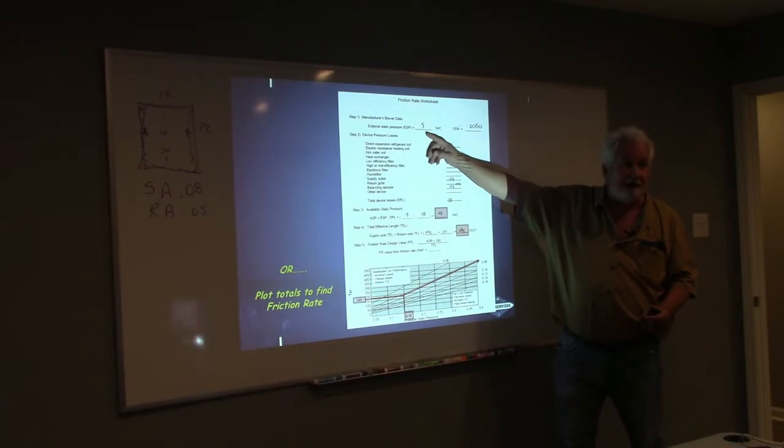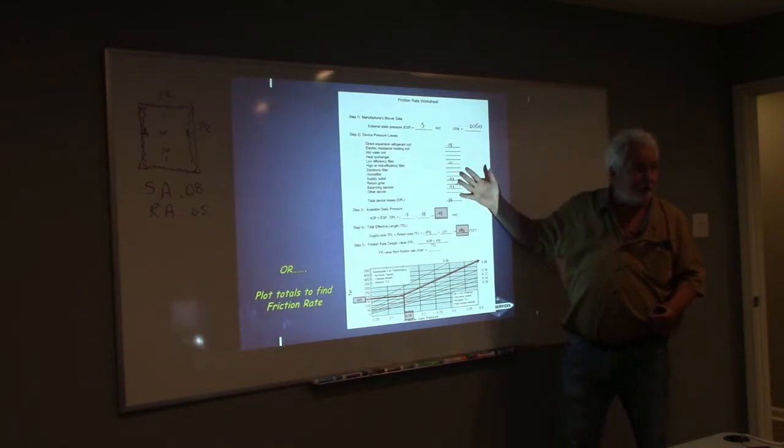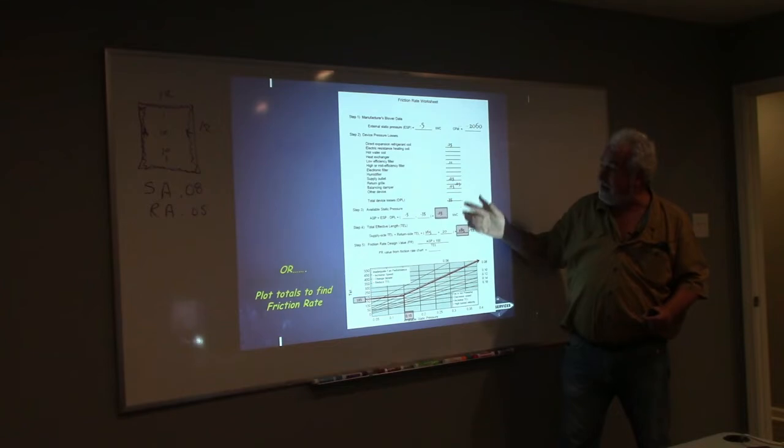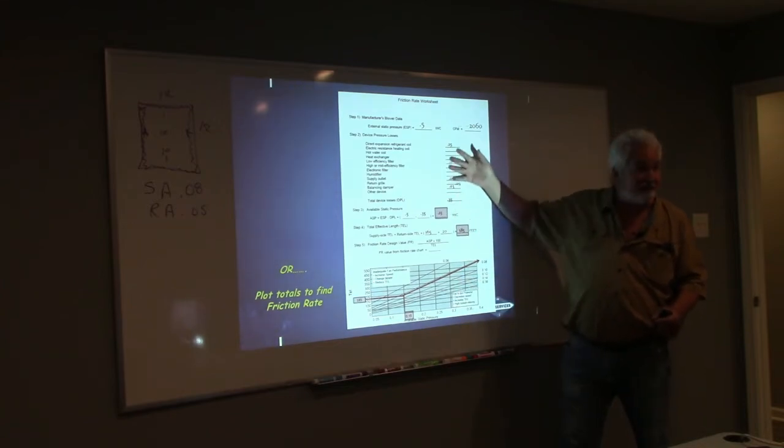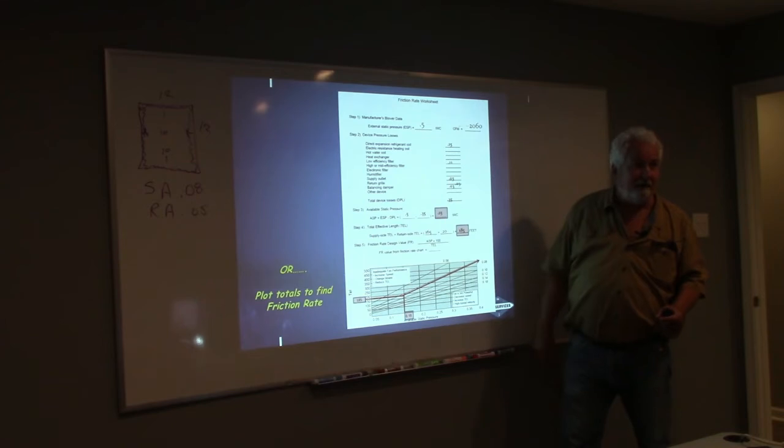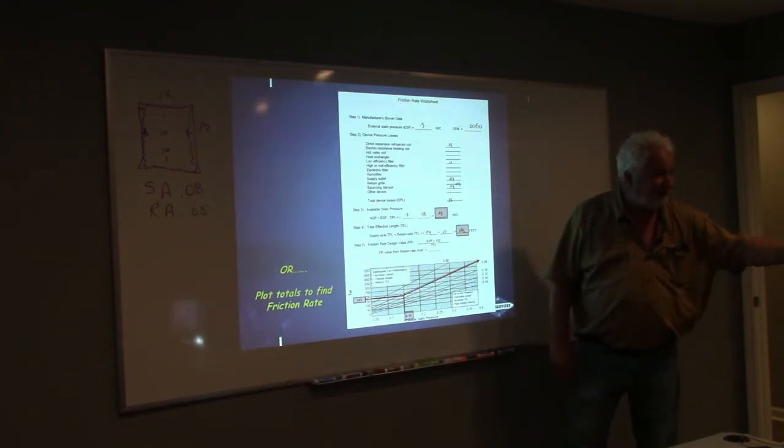What do we have available? 0.5. And you already put more resistance in here. I can't even size this ductwork because I've got more device losses than I have available on my blower. Does that make sense? So my ugly duct got uglier, and in that case, 0.08 ain't gonna cut it.